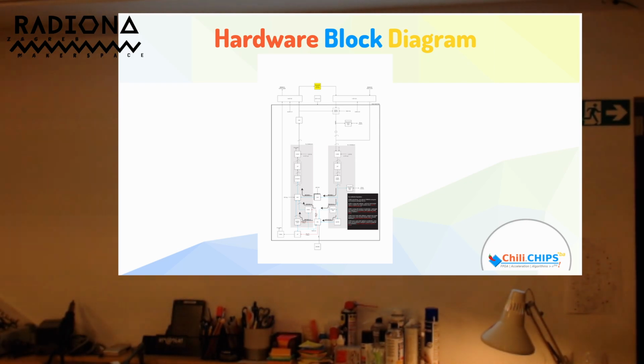This later on is upsampled, and the same process is done in reverse, to get back 65 megasamples per second into the DAC and later on the physics package. So here we need the gain stage, this is the crux of the entire thing, to modify the DAC data that we get so that it accordingly changes the input to the resonator physics package. So it's like a closed loop, open loop here.